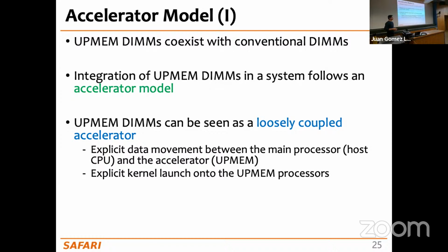It's completely different from, let's say, the instruction-based approach of some of the proposals we have seen here. PIM-enabled instructions, remember, was one of the first processing-near-memory proposals that we covered in the corresponding lecture. In PIM-enabled instructions, we are offloading a single instruction to the PCUs, the processing elements near the memory.